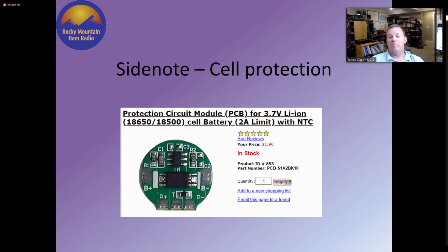So this battery pack made with cells with these little balance boards on them, it would be safe to just hook it up to say a 14-volt DC power supply and just let it go. And what you'll see there is the current will taper off and eventually it'll go to absolute 0 when each one of these little modules cuts the current off to the cells inside.